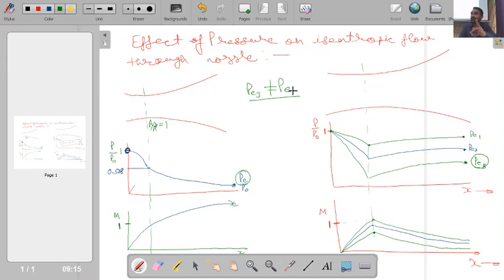Is this point clear? This is an important point, okay, because based on this only we will be having our further discussion. Let me once again emphasize what I am trying to say. If you maintain a pressure difference across the nozzle P naught minus PE, where PE is the desired pressure at the exit as per the relation of isentropic subsonic flow up to the throat and then isentropic supersonic flow in the diverging section.